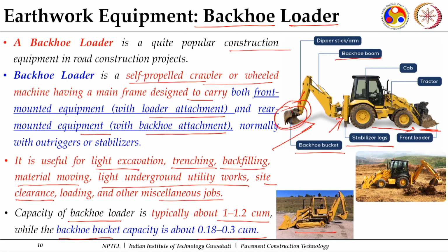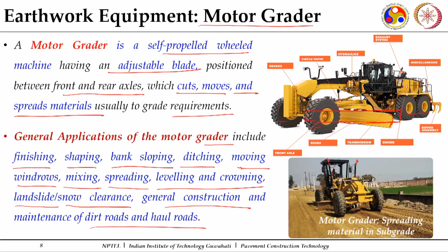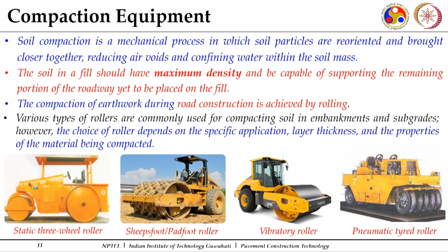You can see there are rippers also there. I'll just show you. Yes, grader. This grader, you can see at the back of it there are rippers. These can be used simultaneously. Many more attachments, rippers can be attached to this particular one, and they can simultaneously serve, harrows can be attached to this particular one, and they can serve other purposes, or they can help us in doing the mixing part. Now, once that particular part is done, the compaction needs to be started.